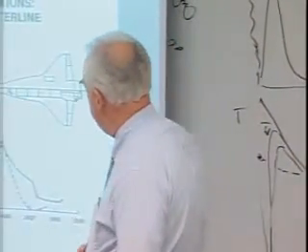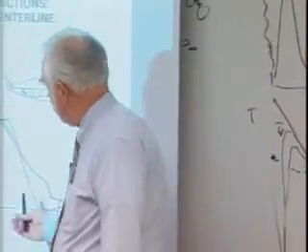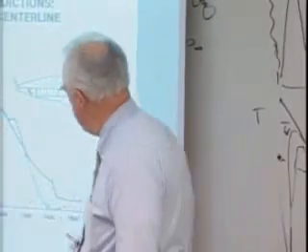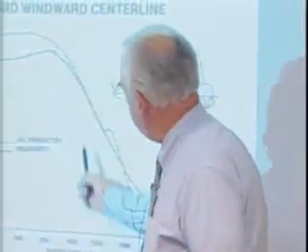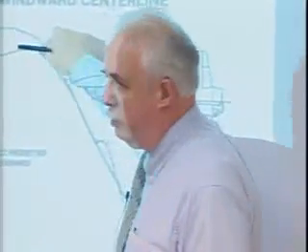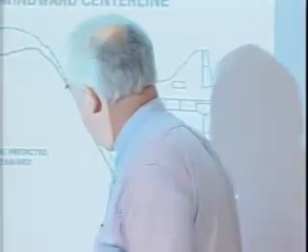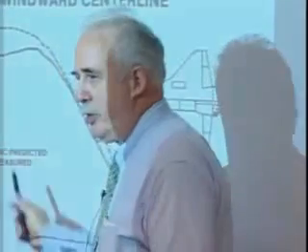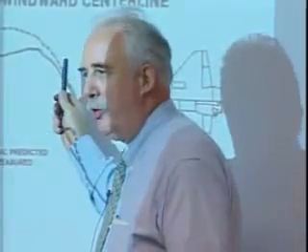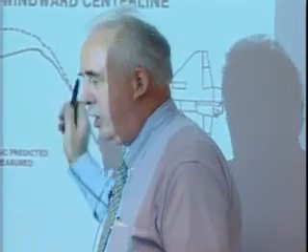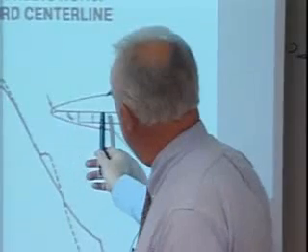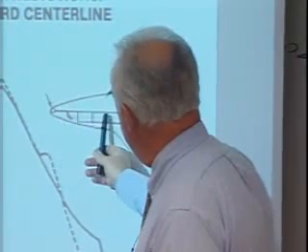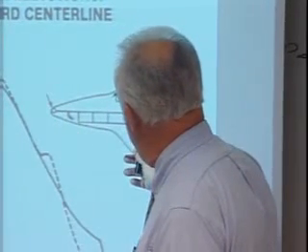Okay, now I'm going to show results in terms of temperature as a function of time. This is the entry time from about 400 to 1,000 seconds. You notice this plateau. You're talking about 20 minutes of entry and 10 minutes of flying it so you don't exceed the thermal protection system. I'm going to show 3 locations: right up here at the nose, just behind the carbon, mid-body, and aft body.